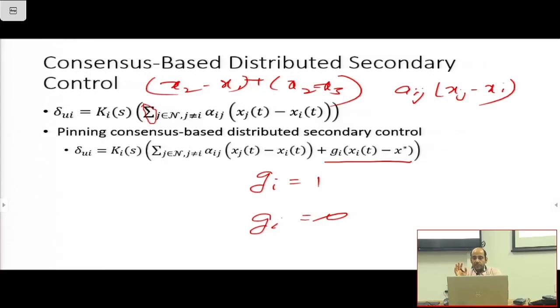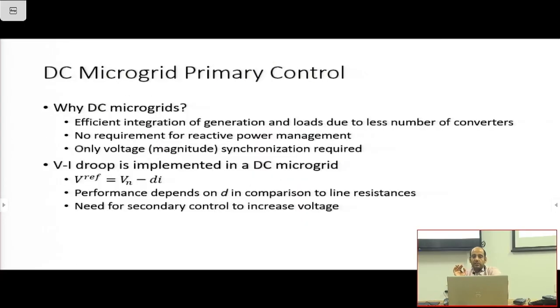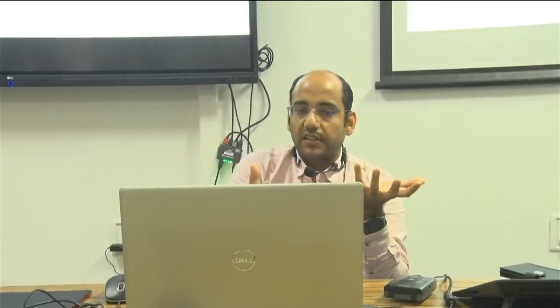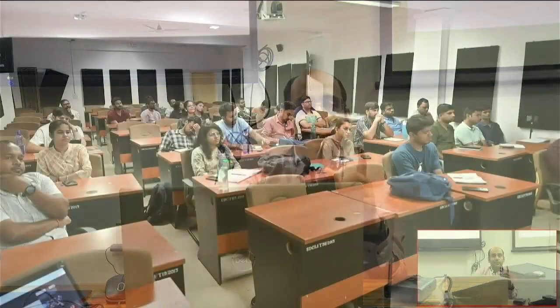Okay. Last 5 minutes. Very quickly, I'll just discuss, not in detail, a little bit about DC microgrid. As I told earlier, DC microgrids, why they are important, particularly for such areas where there is no power system, you can have DC microgrids because they give you the benefit of less conversion, and synchronization is quite easy. When you talk about AC microgrid, you have to synchronize voltage magnitude, frequency, phase angle, all three. Here you just have to synchronize voltage, that's it. Then in AC there is a bigger problem of reactive power management, right?